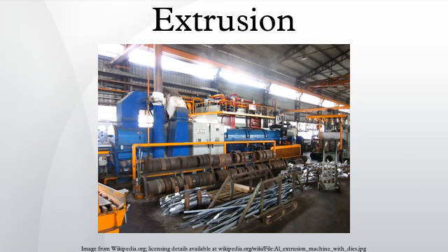If a solid billet is used as the feed material, then it must first be pierced by the mandrel before extruding through the die. A special press is used in order to control the mandrel independently from the ram. The solid billet could also be used with a spider die, porthole die or bridge die. All of these types of dies incorporate the mandrel in the die and have legs that hold the mandrel in place. During extrusion, the metal divides, flows around the legs, then merges, leaving weld lines in the final product.